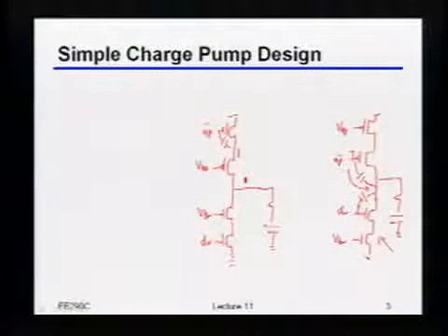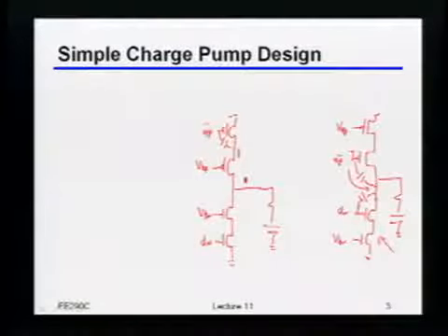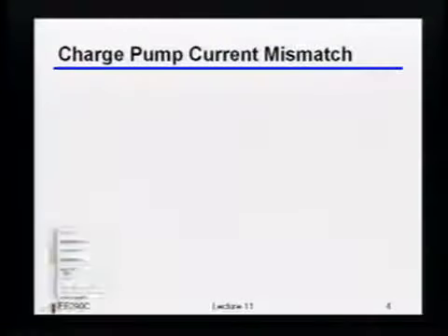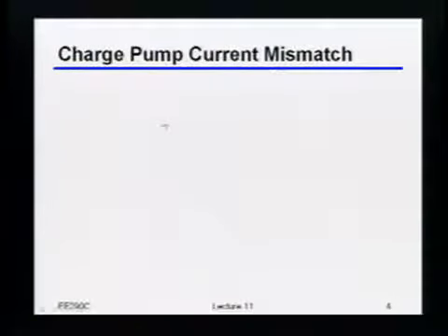Okay, so by the way, it turns out these charge pumps are actually pretty tricky. There are a lot of ways you can mess them up that will screw up the entire PLL. So you really do have to be pretty careful with how you build these things. Just to drive that point home, even if you do all the stuff that I said a second ago, let's look more carefully at how we're really using this thing, and this time I'm going to draw the entire charge pump so that it's really clear what's going on.